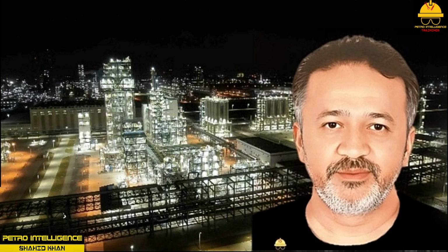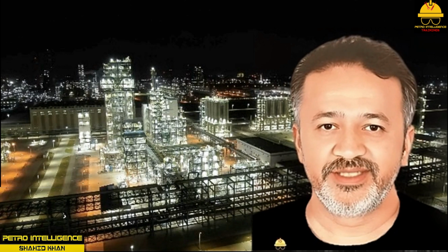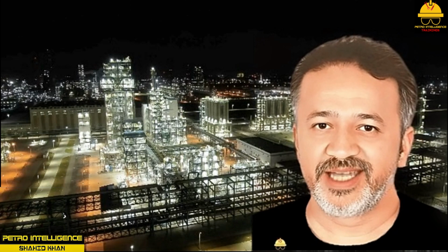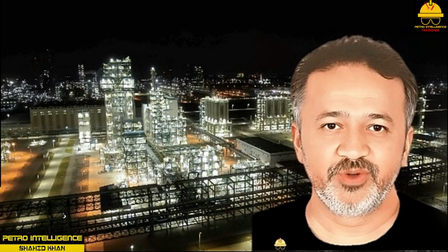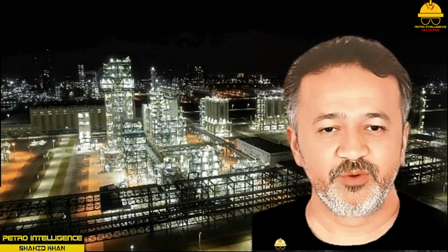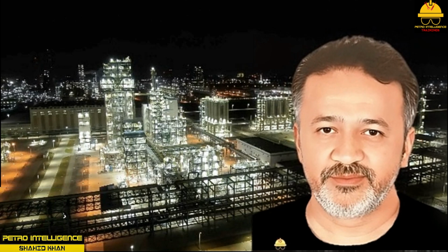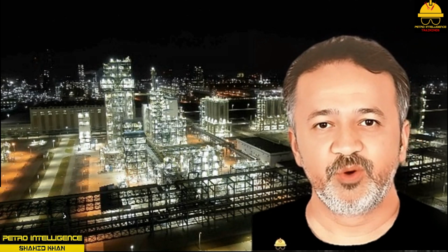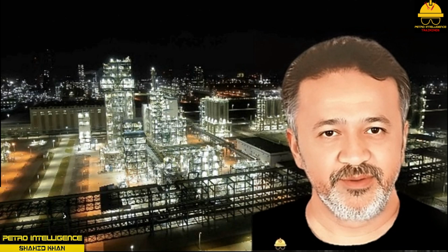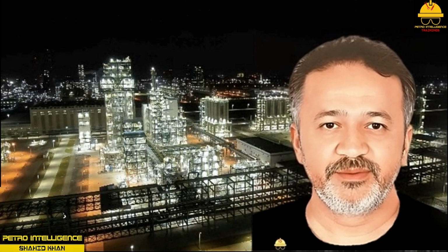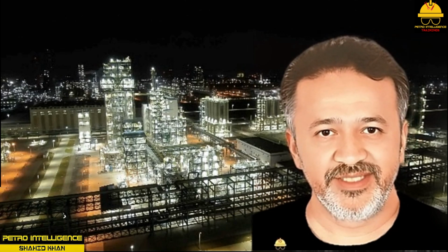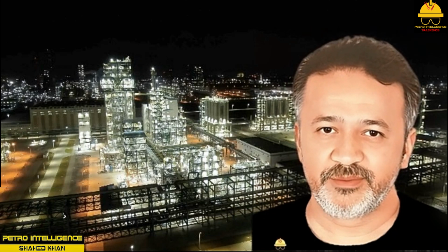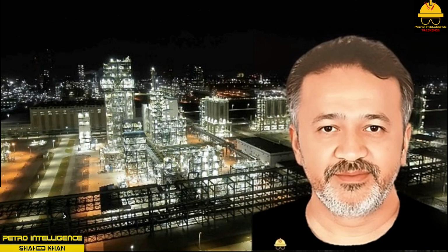Flow control loop. Flow control loops are typically designed so that a measurement of the flow rate is taken first and then the flow is interrupted or controlled downstream. Flow control loops start at the primary element and work their way back to the final control element. Flow control primary elements could include orifice plates, flow nozzles, pitot tubes, Annubar pitots, mag meters, turbine meters, mass flow meters, nutating discs, oval gears, venturi tubes, vortex meters, target flow meters, and integral orifice flow meters. The most common primary element is the orifice plate.